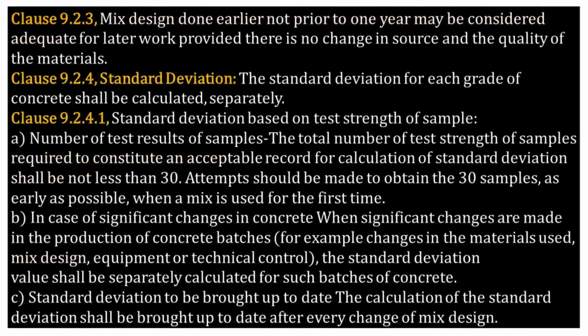Now we'll delve into clauses 9.2.3 and 9.2.4, which deal with two important aspects of design mix concrete: reusing past designs and understanding standard deviation. This slide explores these concepts. Reusing a previously successful mix design can save time and resources if certain conditions are met, as outlined in Clause 9.2.3. Clause 9.2.3, mix design done earlier not prior to 1 year may be considered adequate for later work provided there is no change in source and the quality of the materials.